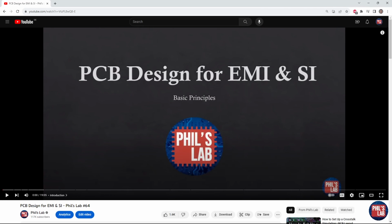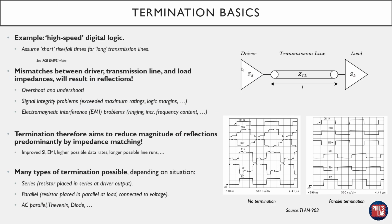If you'd like more detail on how to calculate when something is, for example, high-speed, make sure to check out video number 64 on my channel. In any case, assuming we have short rise and fall times and we have fairly long traces, then we need to be concerned with topics such as controlling impedances and also termination.